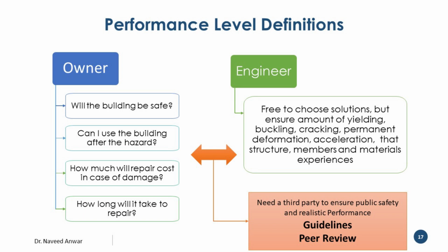So the owner's question: will the structure be safe, which was my question in the first video last time. Can I use the building after the hazard? This is still tricky, but based on the immediate occupancy level or the other levels, we can say yes and no, because we have those four levels. So we can answer this question. How much will repair cost in case of damage? We don't have the answer to that yet. And how long will it take to repair? We again don't have an answer to that. Performance-based design does not answer these two questions.